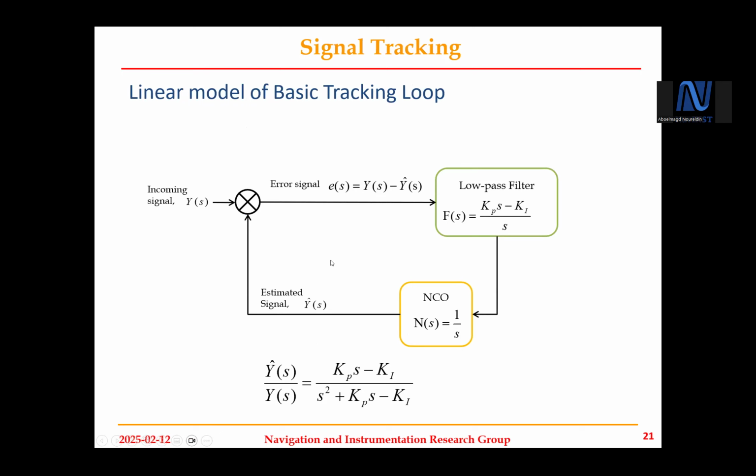The problem looks like a control problem, right? So you have the low pass filter and what we call the numerically controlled oscillator. From here, what's this function? Anyone can guess or knows what this is? In the Laplace transformation domain, what's 1 over S? Integration. Yes, exactly. This is an integrator, right? So this is how the problem is depicted.